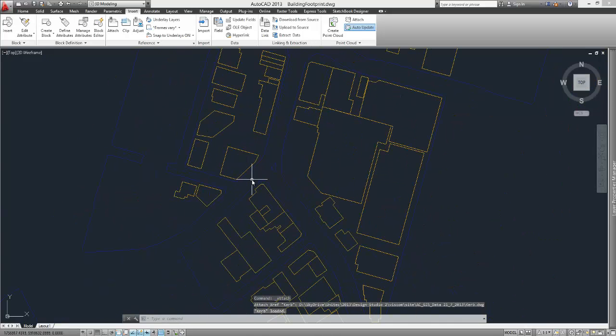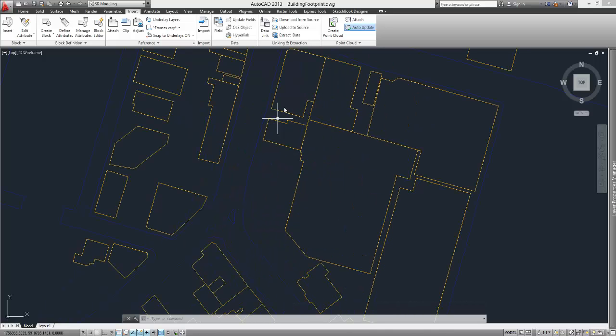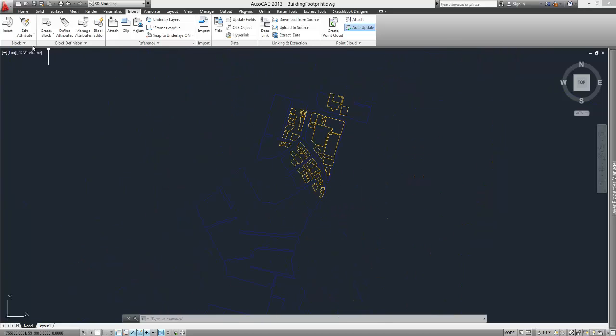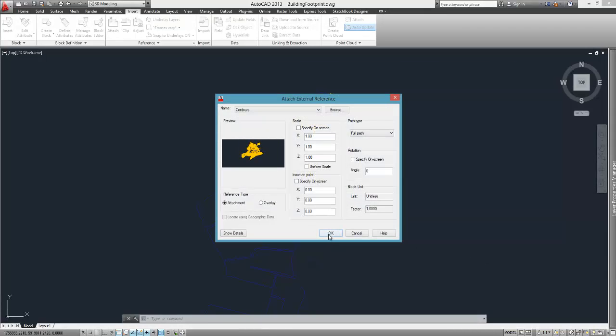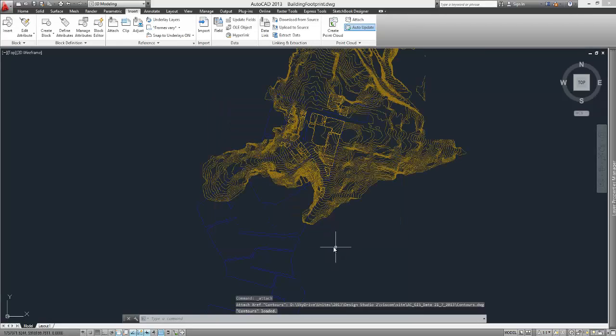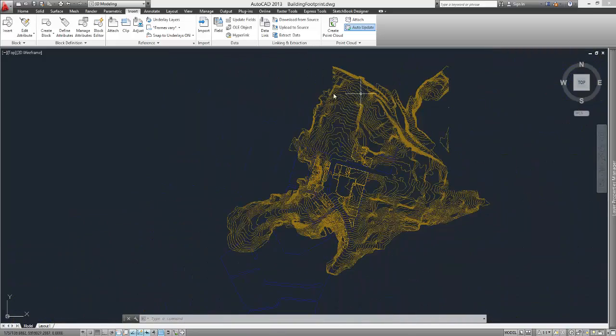Now what I found is my contours, my curb file and my buildings are all in the same place, all in the right place. Now if I bring in my contours as well, same thing, no scale, insertion point unchecked, and OK, and zoom in. We see that this looks pretty sensible. The road being fairly straight, even contours across my site, sort of flattens out a bit and does drop a bit more rapidly as we come around the corner. So that all looks quite good.